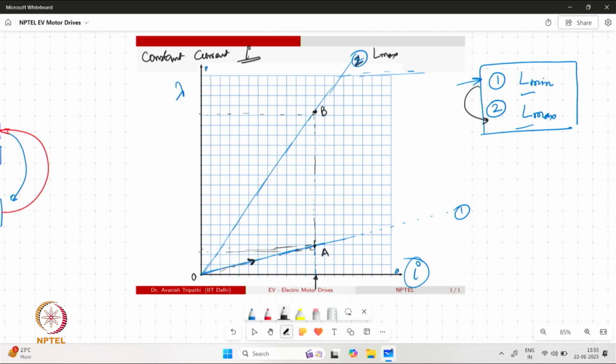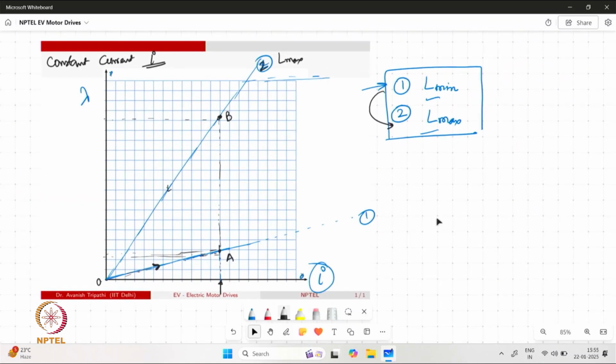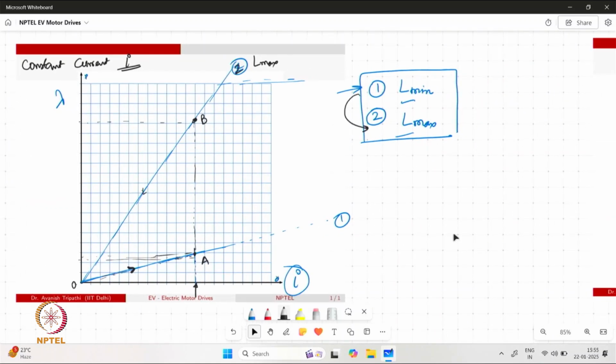So once the plunger is moved, we do have the facility to reduce the current and bring the current down to zero. Now in this whole process, the work done that is happening in the system can be correlated to the energy stored in the system. So whenever we are talking about the excitation and the flux linkage, there is always some energy associated with that, and that can be represented as half Li square, which is commonly known to all of us, and can also be written as half lambda I.